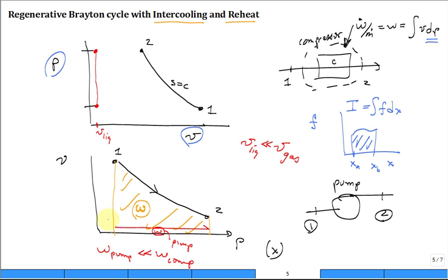You can see it here as well, but when you leave it in the traditional PV diagram, it's not the area under the curve, it's the area to the left. I don't see too many applications where you're looking at areas to the left of the curve, but there it is. And so you see that this work is large and this work is small for the pump. This is for the compressor right here, the work of the compressor. So as a clever engineer, you say, running that compressor is very expensive. How can I reduce that work?